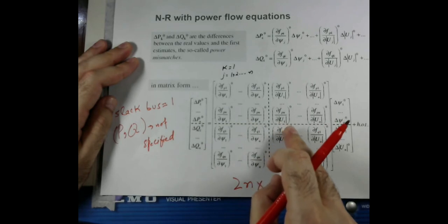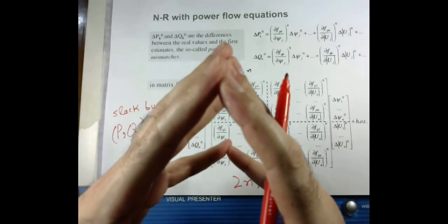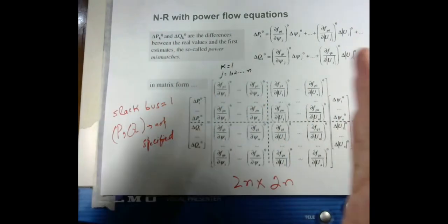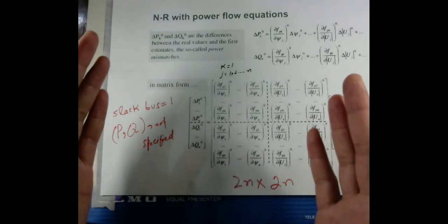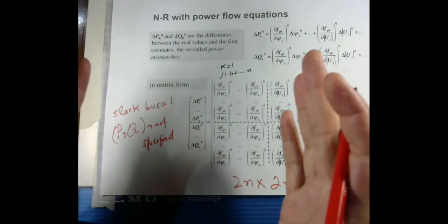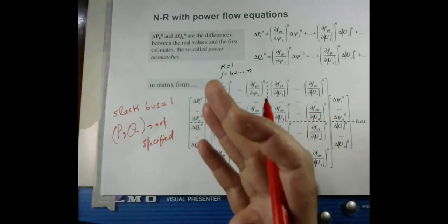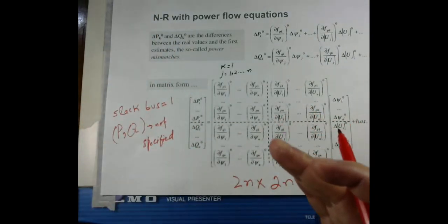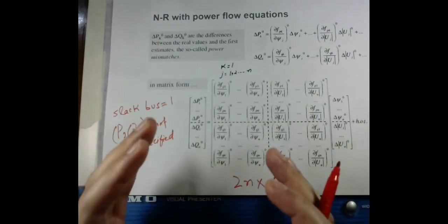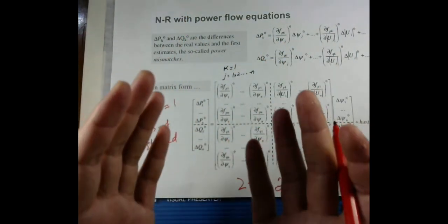So we will remove some terms, and I mentioned that we will learn this method, and we will also discuss which terms will be removed from the matrix, depending on the given parameters and knowing the values on the different types of buses, like the slack bus, voltage control bus, and the load bus. So this matrix will be reduced to some particular number of elements, but we will discuss that also.